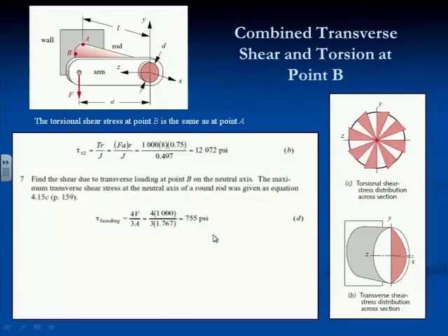And that should not be surprising. There's a rule of thumb that you may have been told in ES 2502 that the shear due to bending, or transverse shear, it's more properly called transverse shear, but a purist would say it's not really due to the bending, it's due to the... Anyway, I call it by either name. So that shear that's from all the pieces of paper trying to skid on one another will tend to be small in a long beam.